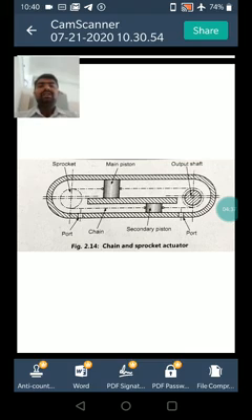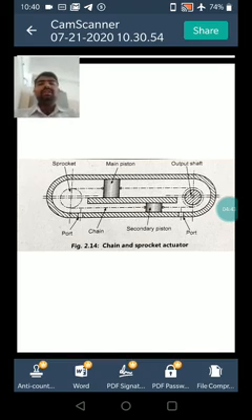The chain is connected to pistons of different diameters. These pistons in their respective bores separate the unit into two volumes. Pressure applied on one side of the piston generates motion due to the different areas of the pistons.